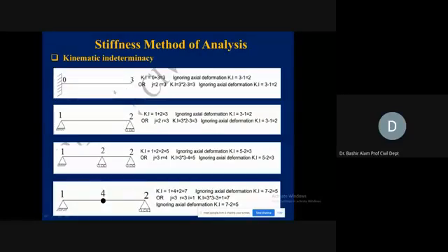Now, if we ignore the axial effect, we are taking out the number of members now here. So ignoring axial effects, 3 was total minus 1, because of this one member. So this is becoming now 2 degrees indeterminate.